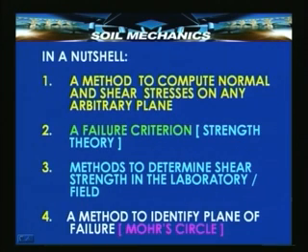In a nutshell, what we have seen so far is that there needs to be a method developed to compute normal and shear stresses on any arbitrary plane, and it is also necessary to have a failure criterion or a strength theory to know whether failure will take place along any arbitrary plane or not.